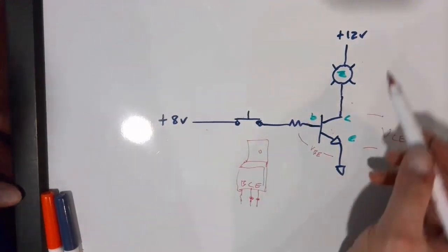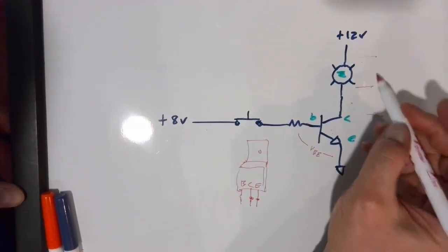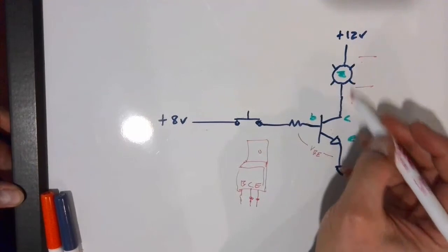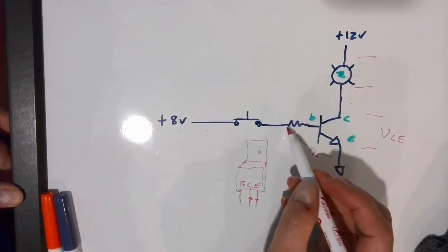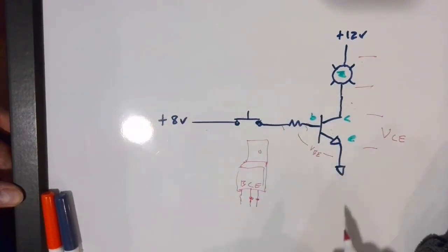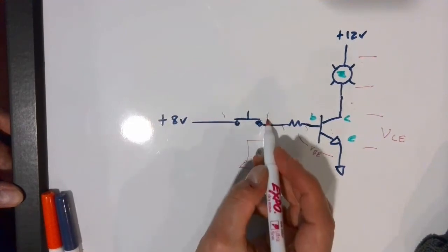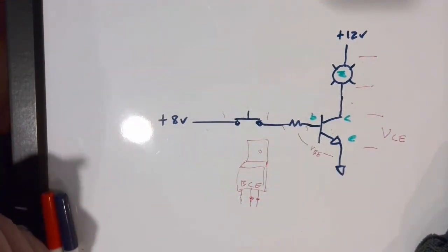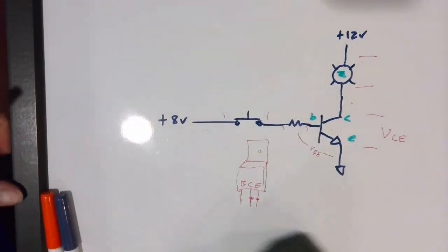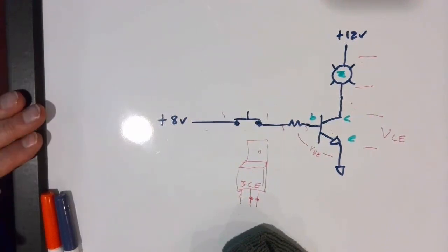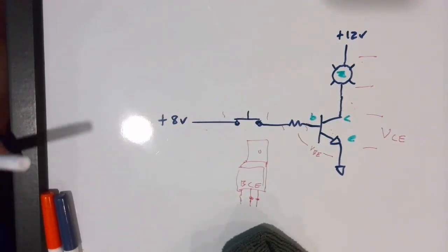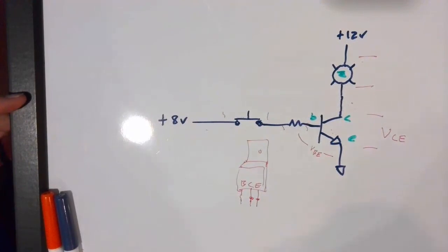The other voltage measurements, if we're trying to just measure the voltage across the lamp, we simply measure between those 2 points there. If we're trying to measure the voltage across this resistor, we measure the voltage across these 2 points. If we're trying to measure across the switch, again, we measure across the switch for voltage. In this lab, you will not be using the meter to measure current the way we have in the past. We're going to be using some calculated values or looking at the power supply to actually see those. So that's in the lab video.